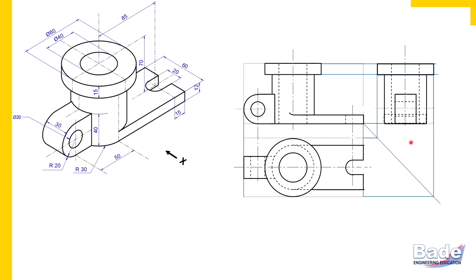Now this plate has a slot also. This U-shaped slot we have already drawn in the front view. Now simply draw end projectors and complete that slot. Watch here, this small dotted rectangle here. This is the slot in the side view. Of course, it is hidden. So this is how we have completed the 3 views of the object.